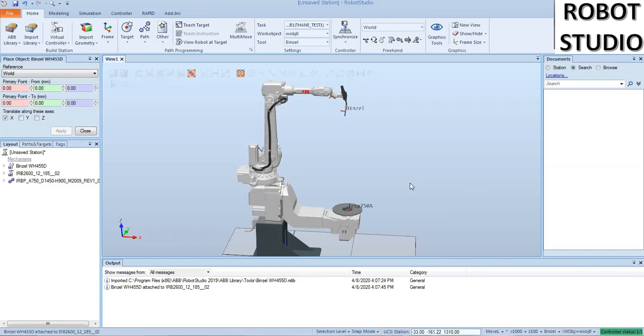So if you were to put some tooling on this positioner with a part, a lot of times people have a flat machine surface with an XYZ planar coordinate system defined by tooling pointers. And what would happen is when you got that fixture into your robot and secured in place in the headstock, then you would teach that object frame on the fixture itself. And once you set the parts in there and program your parts, say you were to get a different part with a different fixture, you could unload that fixture, put in the new fixture, and reteach a new work object for the second fixture. But if you ever came back to the first fixture